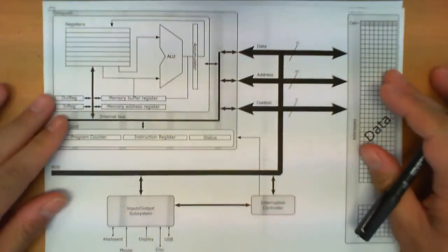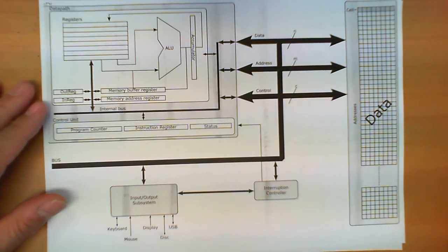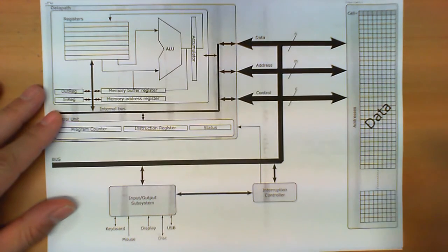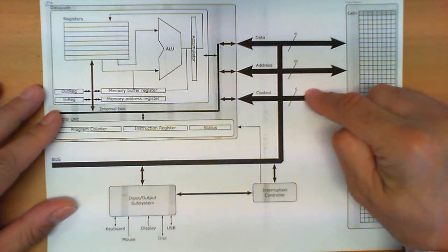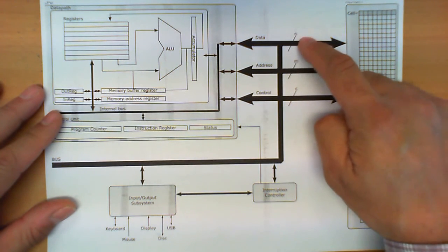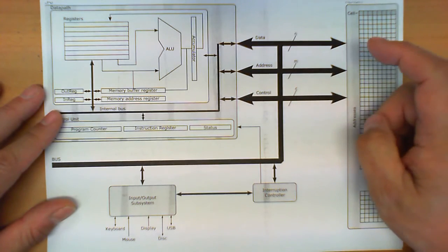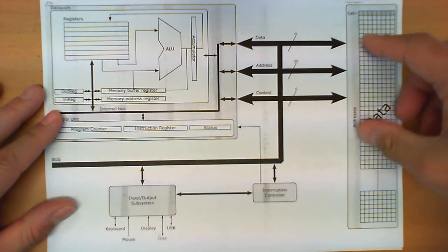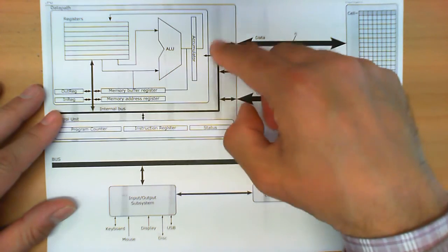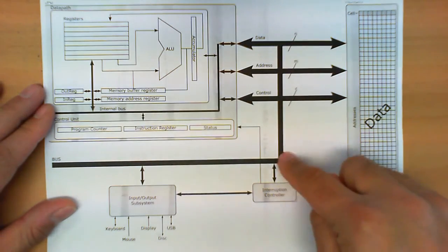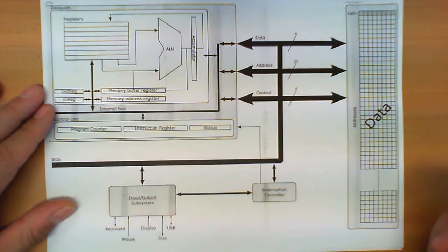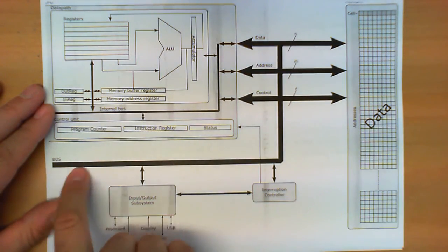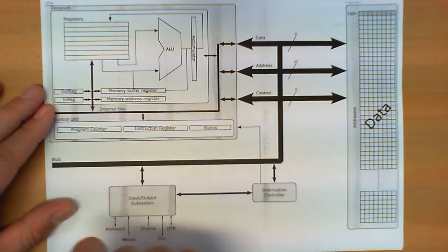Now we go back to our image of the data of the computer system. We can see the advantage of having a bus to communicate three elements: data, address, and control signals. These three buses have different widths. Here we have N, M bits, and C bits, but these three signals reach both the memory over here and the microprocessor. Within the microprocessor, they reach different places, the interruption controller over here, and also the input-output subsystem. So this is the situation in which 1, 2, 3, 4 major systems need to exchange a lot of signals, and therefore the most appropriate decision is to use a bus.